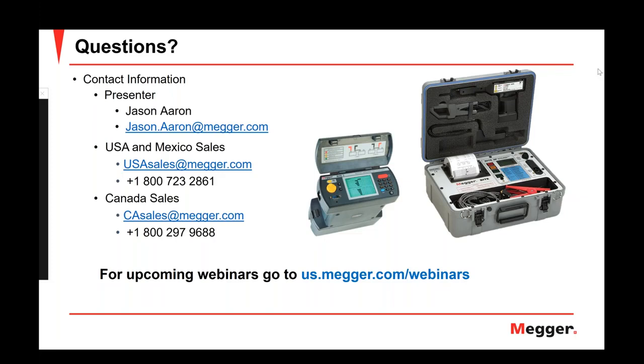But that doesn't mean you cannot test the battery string. You will need to sectionalize, which means dividing the string into two parts. In the case of 480 volts, the voltage across each part would be 240 volts, which is within the instrument limits. Then you can carry out measurements on each of those sections separately. The results won't get affected, but you will just need to do this sectionalizing to be able to get all the measurements.